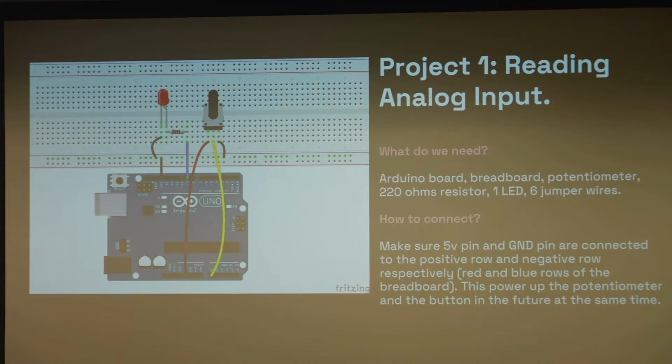You're going to see that we're going to do it so we can adjust the brightness. And you need to make sure that all the time you use the specific resistor for the LEDs. Again, remember that, as we saw in the previous workshops, the larger leg of the LED is going to be connected to the positive side, in this case our digital pin, and also connected to our resistor, and on the other side is going to be our negative energy or our ground pin.